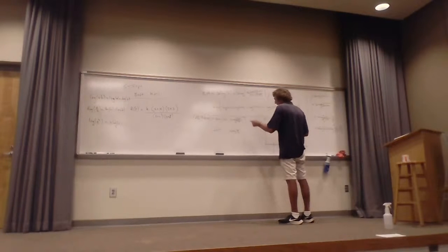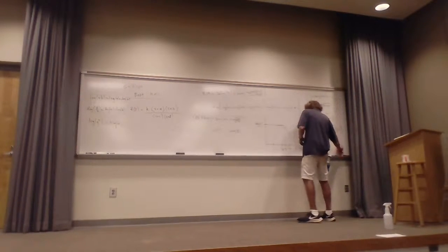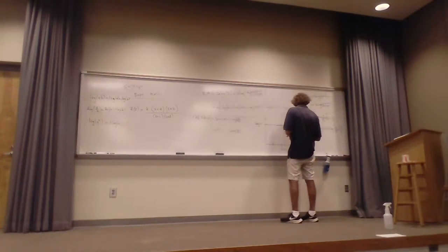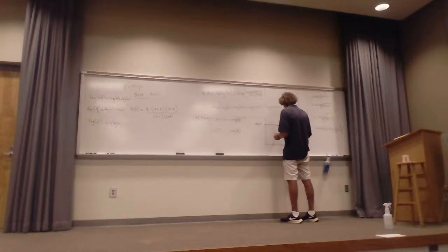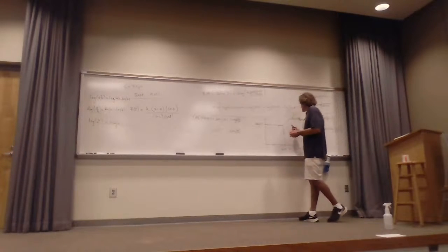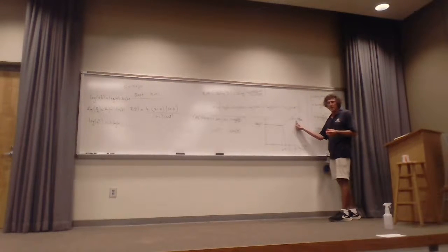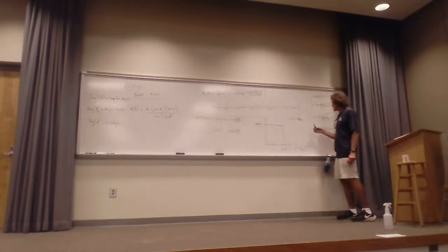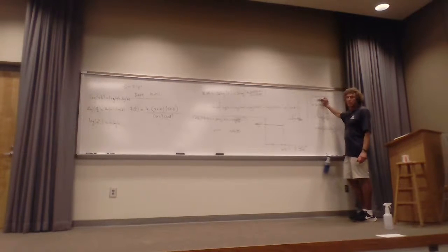So actually, I've got it decreasing here, but technically this one, because it's a zero, it's going like this. Now it starts going up at plus 20 dB per decade. Usually you'll just see a plus 20. If you're getting correspondence from people and doing engineering, you'll just see plus 20. It's implied dB per decade, and that's going up. So that's what the Bode plot of that would look like.